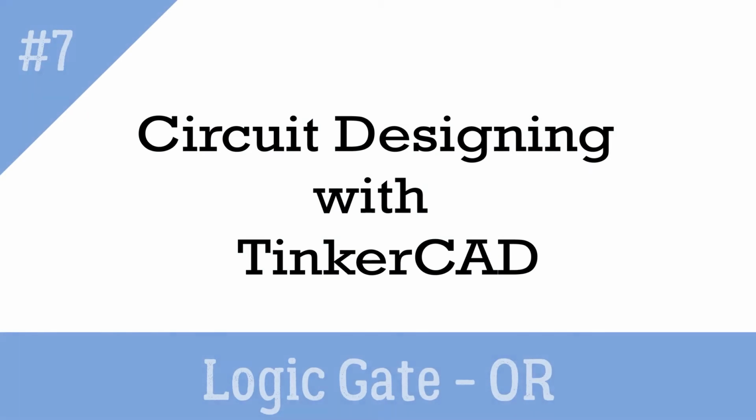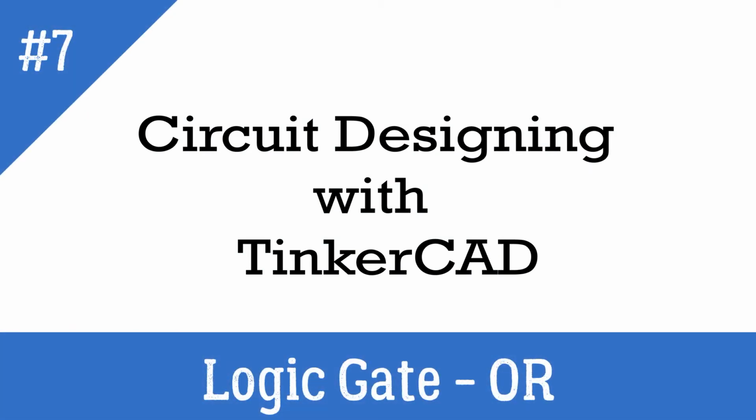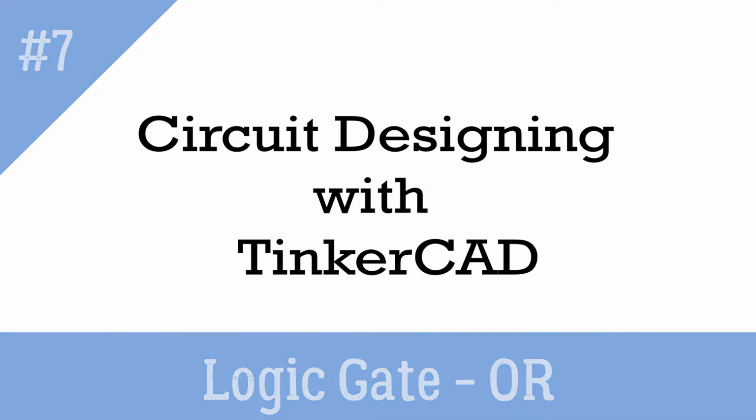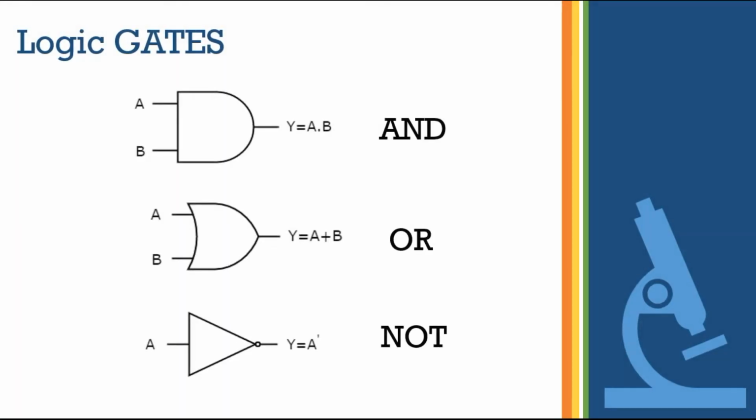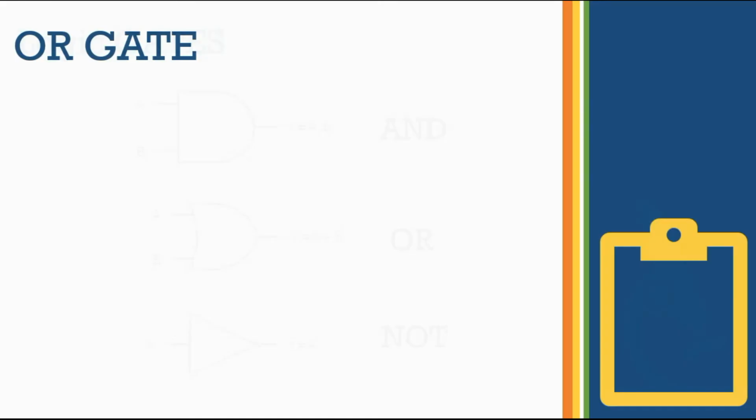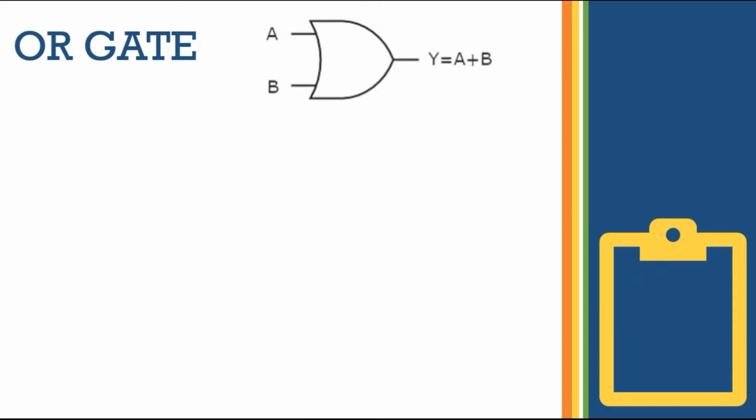Hello and welcome back. In this lecture we will discuss the logic gate OR. We have already discussed the AND gate, now let's explore the OR gate. Same as the AND gate, the OR gate also has two inputs and a single output, and it performs logical disjunction.